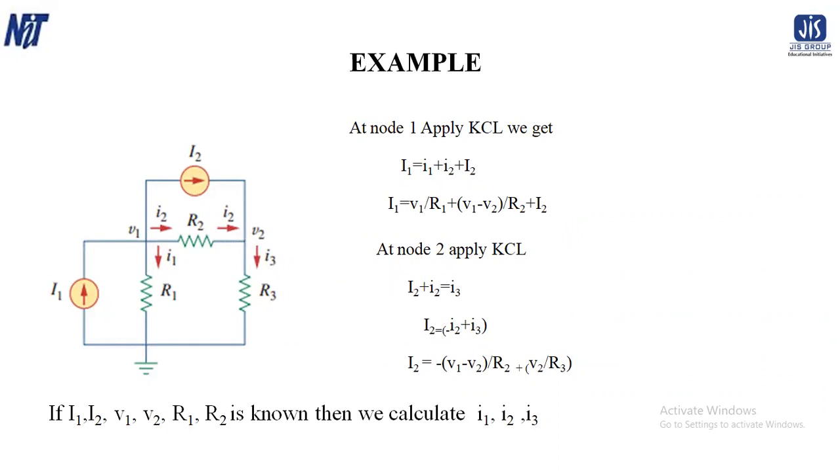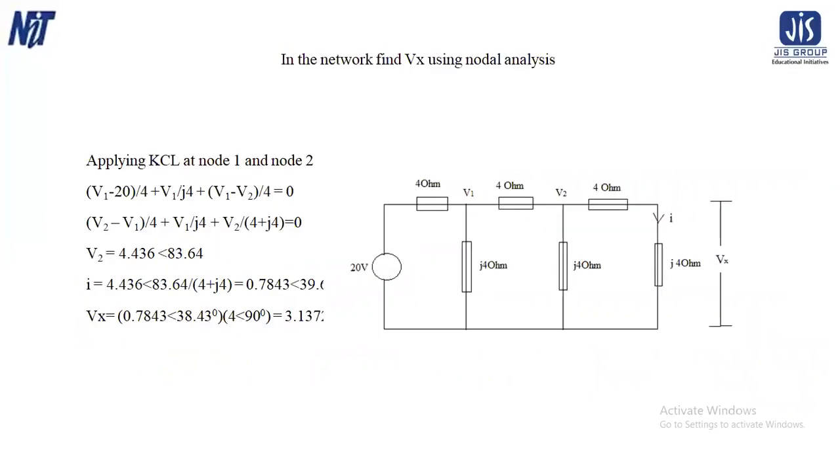The problem of node analysis is a very crucial type, and here we need to apply the KCL. So the process is, first consider a node, then consider the voltage of that node, then find how many branches are connected with it, then find the individual branch currents, and then check how many currents are coming in and how many are going out from that particular node. The summation of all the incoming and outgoing currents should be equal to 0. In this way we can find the voltage of that particular node.